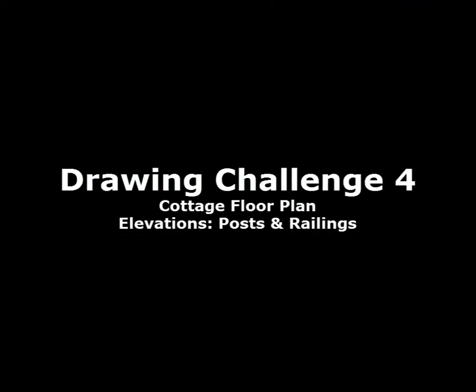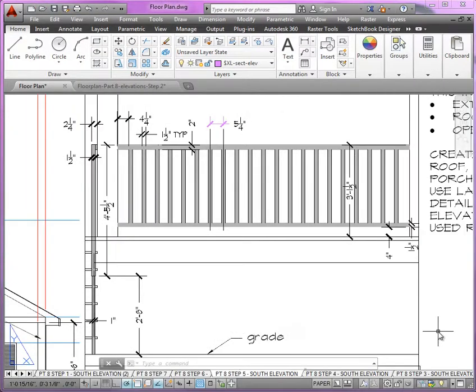So now we're going to take a look at developing the railings. If you refer to your notes, you can see here all the dimensions you'll need to lay out the railings. Keep in mind that we're going to use a hatch, a solid hatch with color 255 or the no plot color, just so we could hide the line work of the remaining elements that belong to the window behind the railing. We want to make the railing look or appear to be in front of the windows.